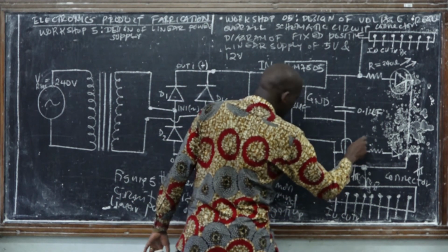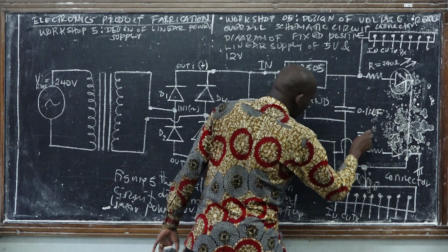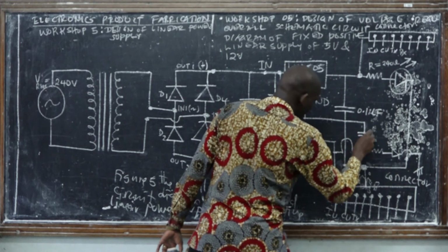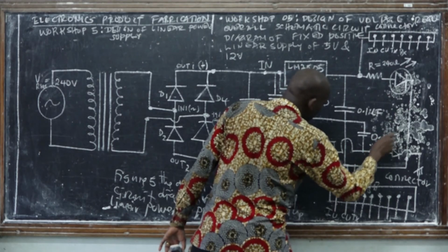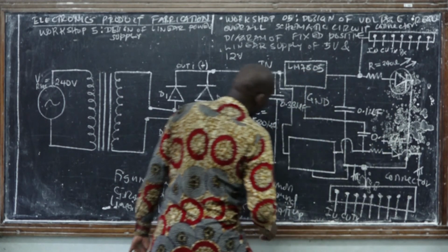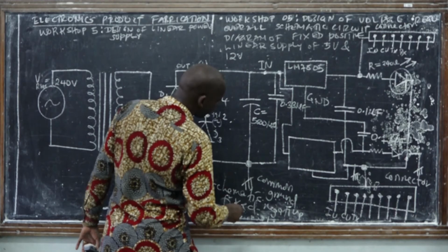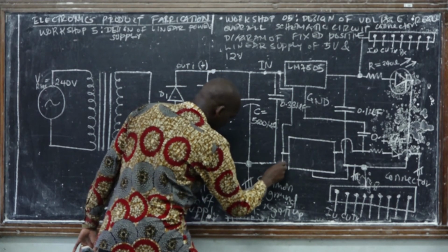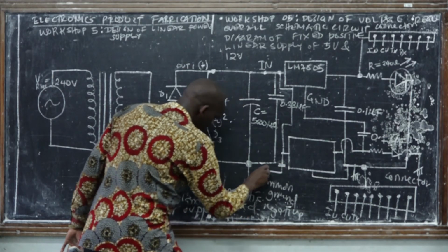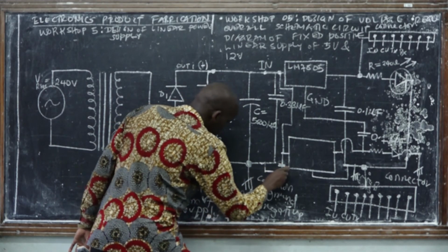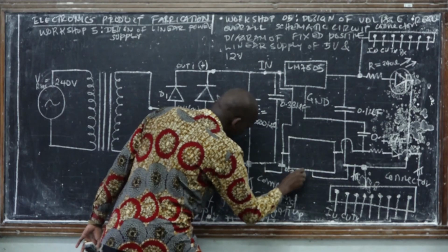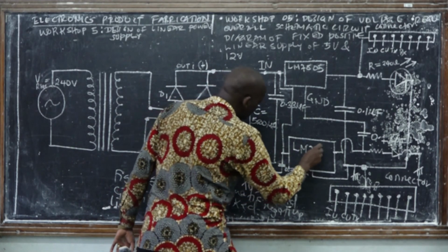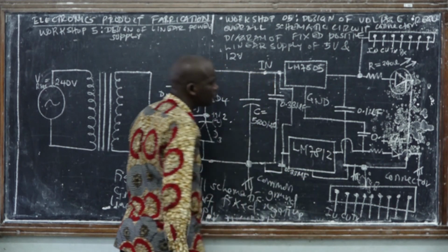We have to connect it with a capacitor of 0.33 microfarad. And for this side also, we have to connect this input with a capacitor of 0.1 microfarad. So this possibly is LM 7812.